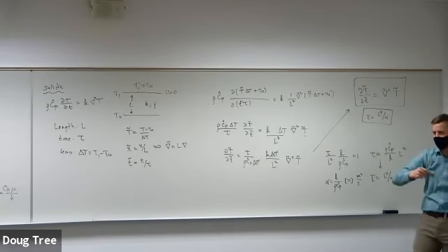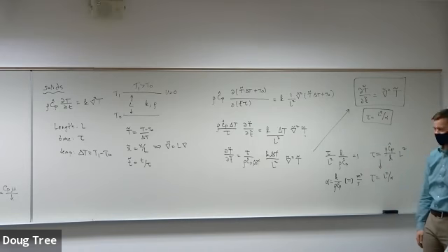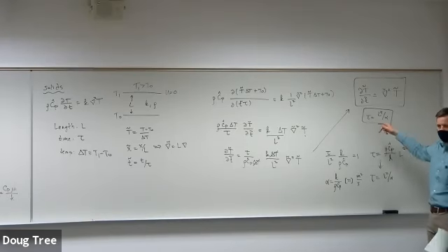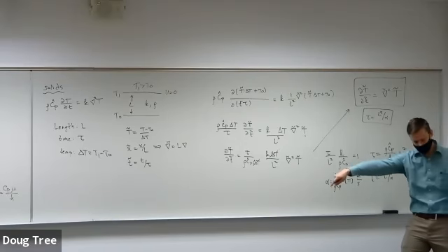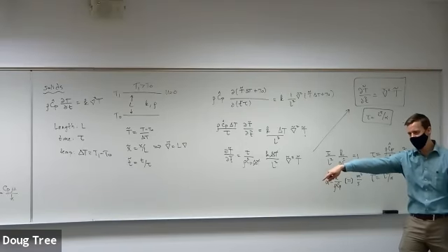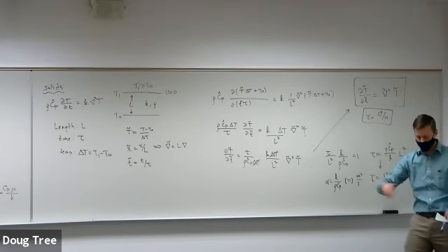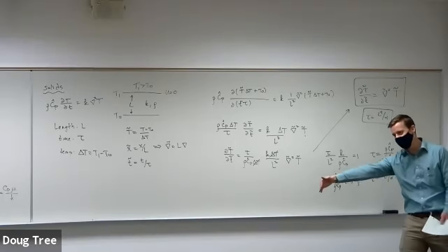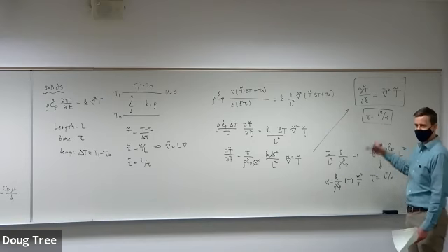So what this tells me is that if I have something diffusing, there's a characteristic time that it takes to go the distance that it's diffusing, and it goes like the distance squared divided by the diffusivity. So if I put some stuff here, and I look over here at a later time, or if I look at some length, I have some idea about when it's going to reach that point. Okay, this is the characteristic time scale. Now, if I want to know the exact time, this is going to be proportional to that time scale.